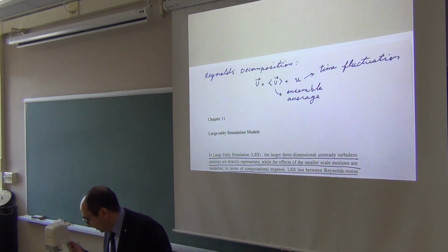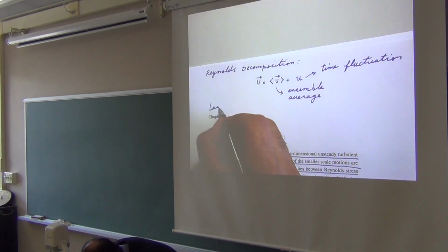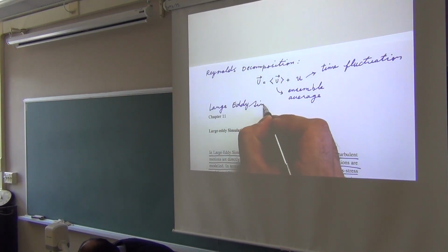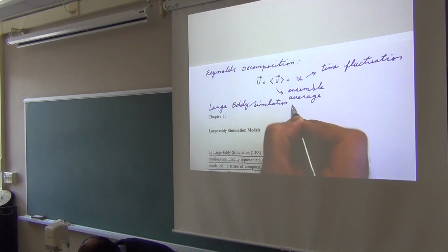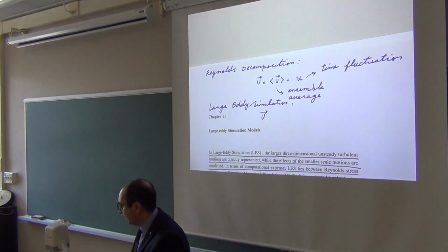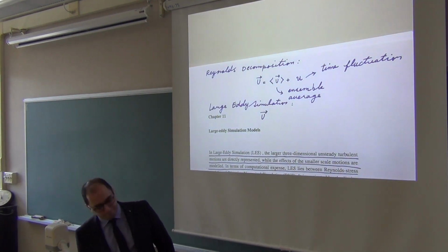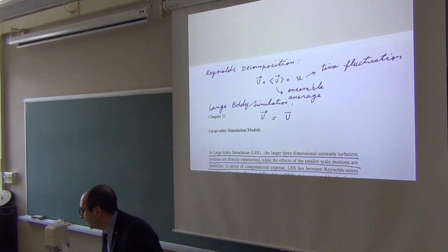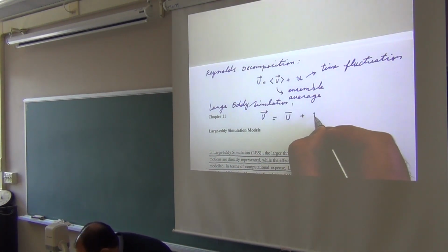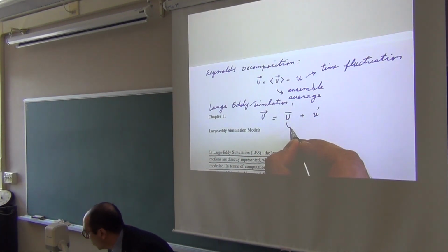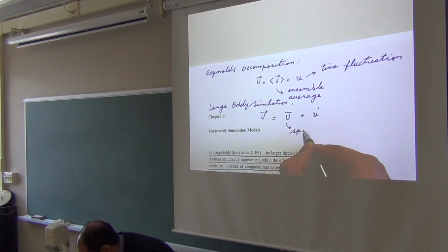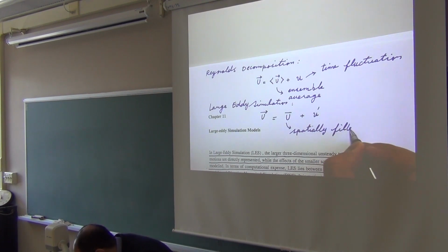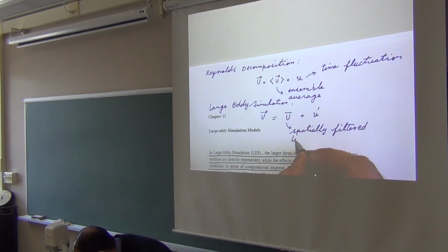However, in large-eddy simulations, it's still the same signal U, but you show me U bar plus U prime. It means totally different things. This is now a spatially filtered field. It's still time dependent.